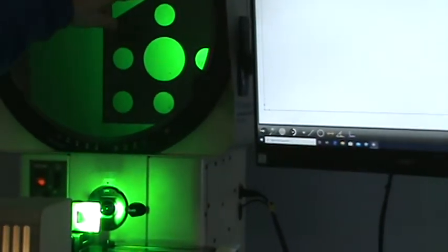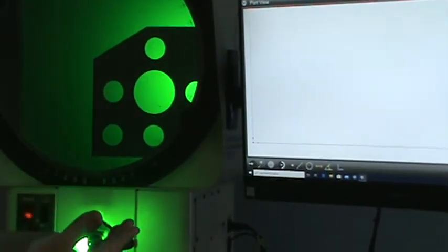All right, so now we've got this line right here on this surface. Well, we want to measure that. So rather than telling the machine that I want to measure a line, the software is also capable, if I just go across the same spot twice, it'll automatically start measuring, and it'll be able to identify what I'm measuring.